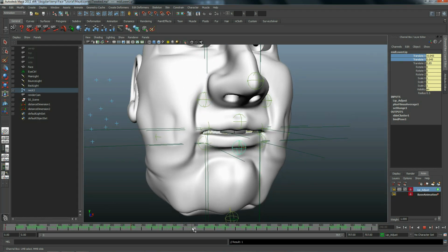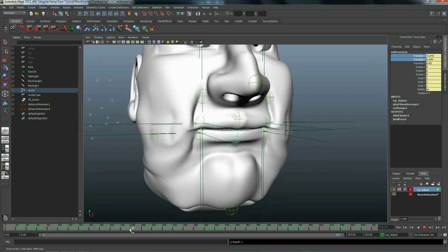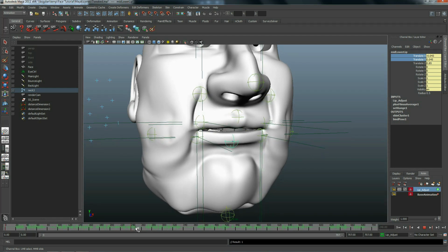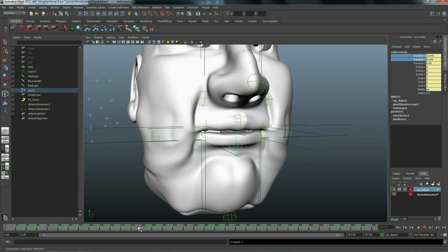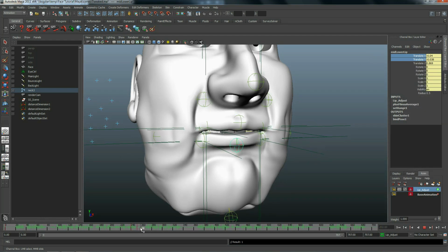Select the mid-lower lip. Make sure that the recently created animation layer is active. Now create keyframes for the bone to help emphasize some of the sounds. Pay particular attention to sounds containing F, P, M, and B.